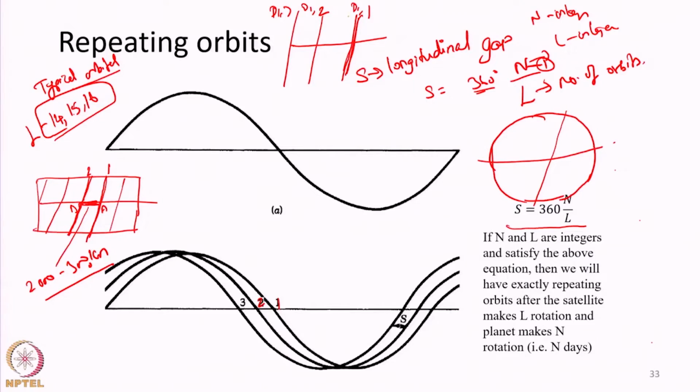So, what will happen? A satellite will have a definite swath width of coverage. The gap at the equator is around 2000 to 3000 kilometers. Whatever the satellite can cover, let us say this is the swath width the satellite can cover, okay. What I am drawing in green color is the swath width. So, from one overpass, a satellite can cover only a definite swath width, that is fixed by the sensor parameters, the scan angle or the push broom geometry, whatever. So, this is limited by the sensor characteristics.